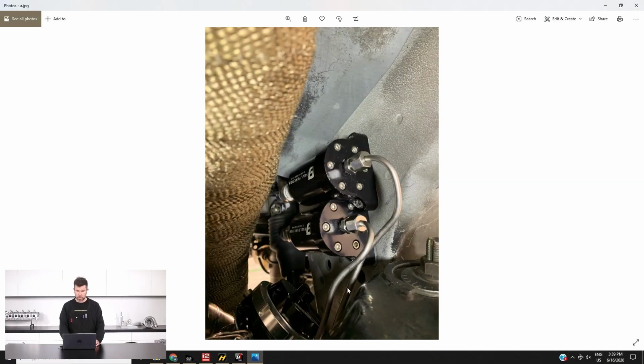Let's just start with this one here, which is probably a pretty poor shot. This is the chassis rail of our FD RX7. So we've actually got 2 exhaust manifold pressure sensors on this, one for each rotor. And you can see we've got some stainless tube coming off the base of these canisters. I'll talk about the canisters specifically in a minute because those are important. That tube then runs up onto the turbine exhaust manifold, and Brandon's put a couple of loops in there. So the whole idea there is just getting the heat out of that.